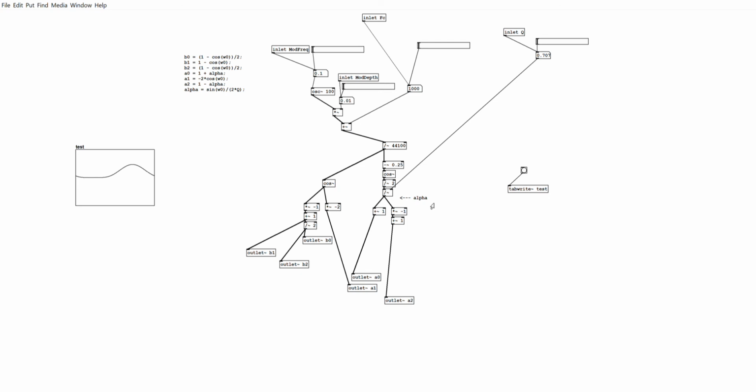Again, as we've said, even for these basic mathematical operations, these are some additions here, you need to make sure that you're using the signal versions of these simple mathematical operations. And the patch wires denote whether what's being transferred between the blocks is a signal or not. So you'll see that this is just a value, it's a float, it's a number. This is a thin line. FC, when it comes in, is just a number. And then what we're dealing with here are all signals. So this is a thick black line.